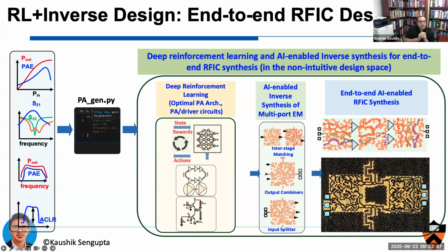The idea is to develop an end-to-end RF design flow that's guided by ML algorithms. The entire process, which is transistor and EM layout aware, navigates through the design space while learning trade-offs between topologies and parameters, and proceeds towards an architecture, parameter, and layout that meets all target specifications. That's the high-level objective for the project.